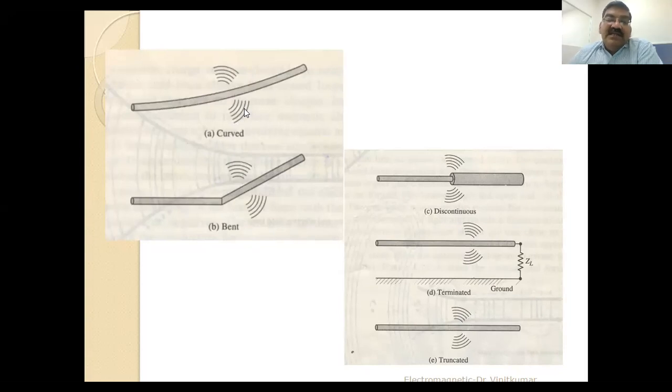So in designing the antenna, this is the aspect: if you look at an antenna, it will have curves and some bends. Or if you have a discontinuity, for example the diameters of the two wires are dissimilar, again the radiation is there. If you have a straight wire carrying time varying current, the radiation is there. But if you have a curve and bend, the radiation improves.